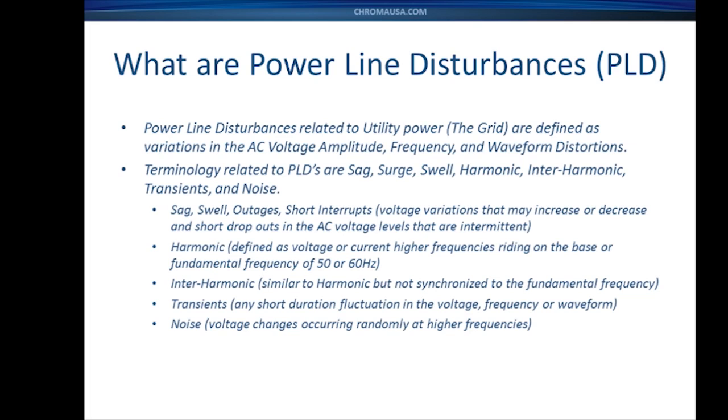Transients can be very short interruptions. Fluctuations in voltage can also be a transient frequency or even transients in the waveform itself. Noise is high frequency content also riding on the standard or base frequency voltage, and it can vary into higher frequencies and be of very short duration, and it may be random also.